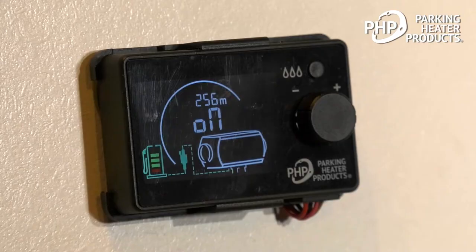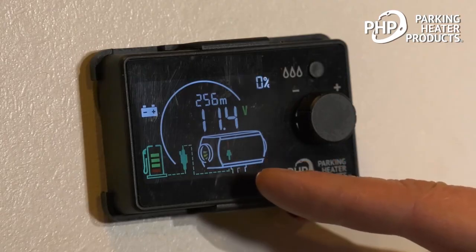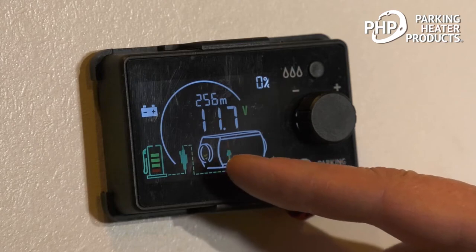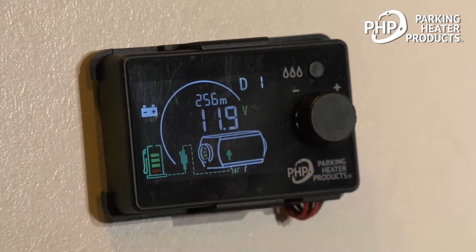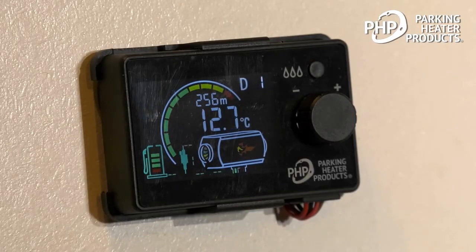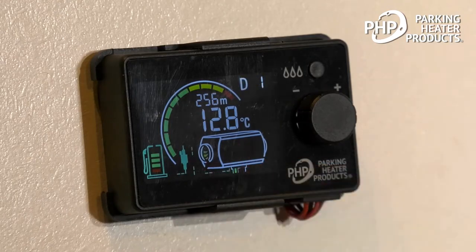Upon startup, the heater's ECU does a systems check and then the glow pin is activated for preheat. After approximately 20 seconds, the blower starts to begin and to introduce combustion air, and the fuel pump starts pulsing to deliver fuel. Once an acceptable change in temperature is achieved, the glow pin is switched off. At that point, any new fuel entering the combustion chamber is ignited by the existing flame.